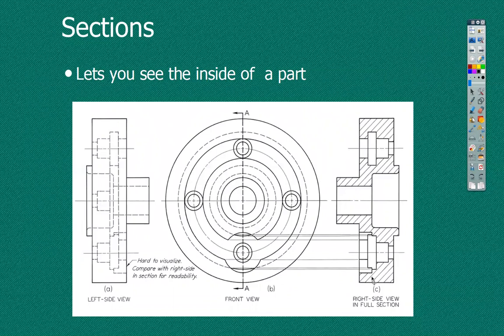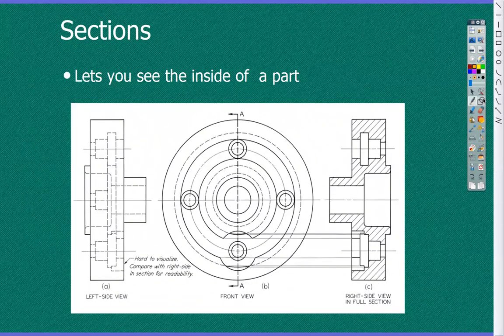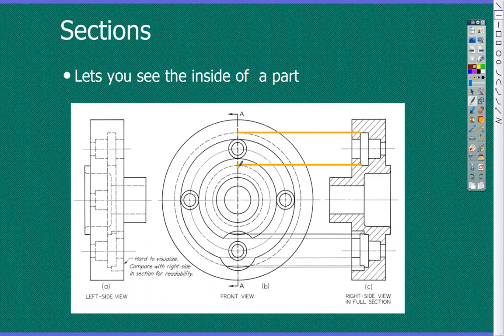This is a kind of complex piece, but we can see that this point goes to that hidden line, that one goes to that hidden line, and those two go all the way around. So that lets us know that this piece is that same rectangular slot that goes all the way around. This is the top opening, but it's also the same width as this counterbore.